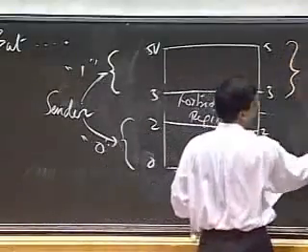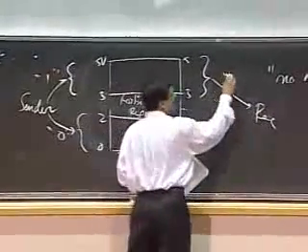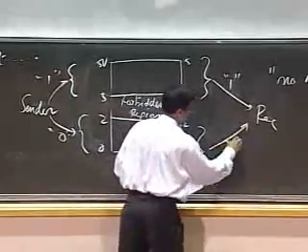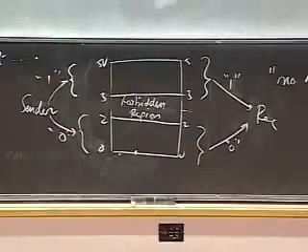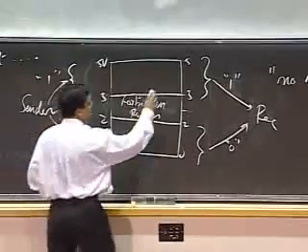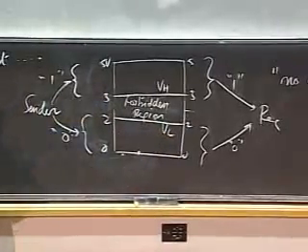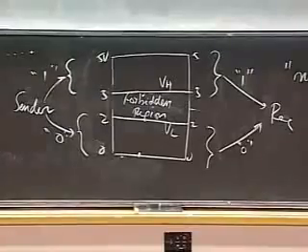At the receiving side, if I see any value between 3 and 5, I read that as a 1, and any value between 0 and 2, I read that as a 0. I may label this threshold VH and label this threshold VL. So there's a high threshold and a low threshold. So this solves one problem.